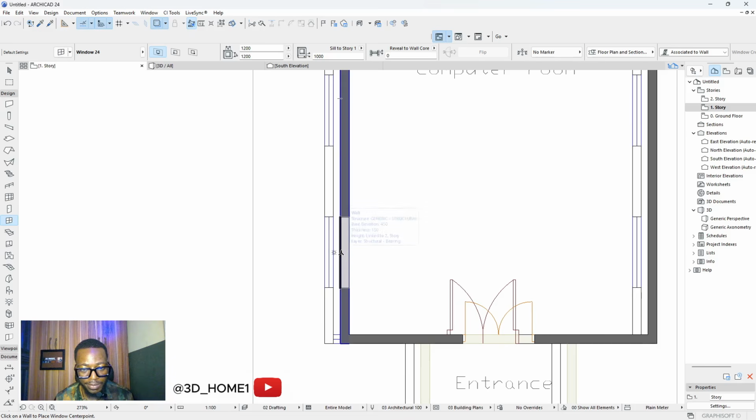So now I'll just click here. First thing, very, very important, we need to do before I do any other thing, the sill, let's make it 900. And then this reveal to wall core, I want the door to have recess, the window to have a bit of recess. How do I explain that? Okay, I think I will just show you.